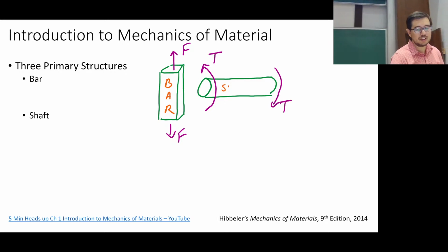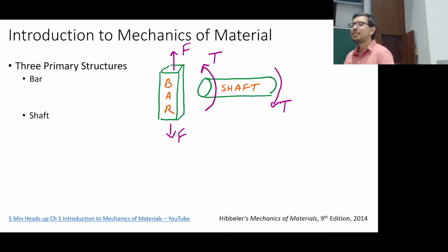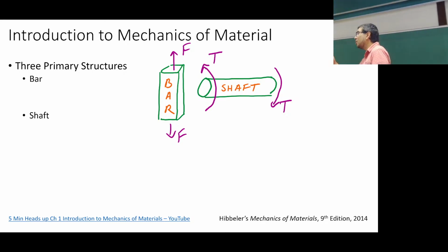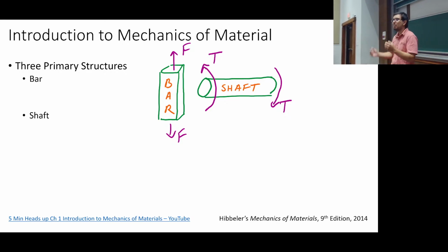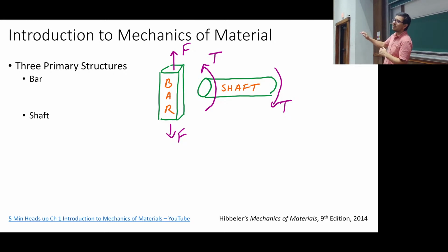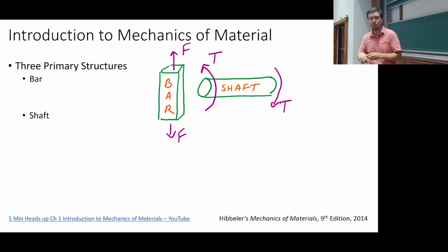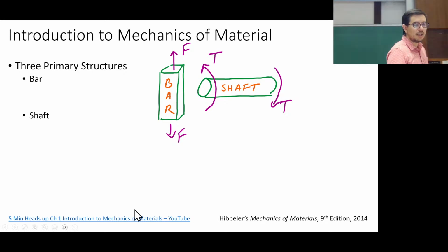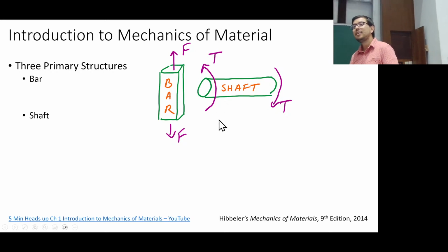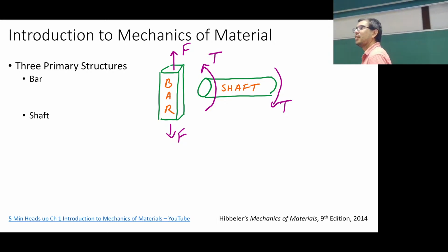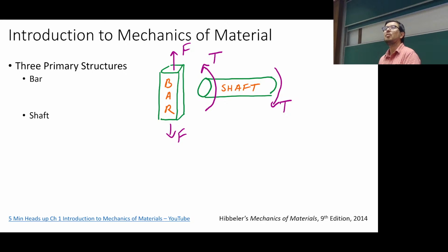Okay, the shaft. Why is this not accelerating? Because the sum of the torques is zero. Right. Okay, and we're going to talk about this. You remember your nomenclature, right? You've got the vector coming out of the face. All right. We're going to cover this at length, ad nauseum almost again, because that seems to confuse people. But if I'm looking at this, would you say that this is a positive torque on this end, externally speaking, or a negative torque? Would that be positive if you're looking at it from the direction of that face?